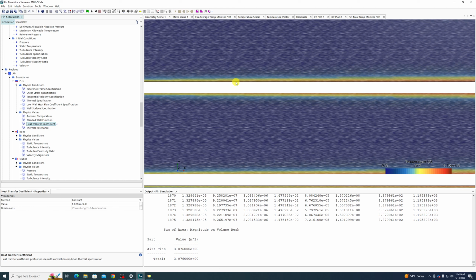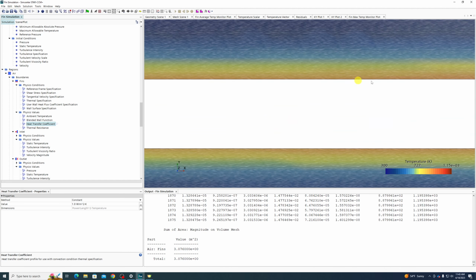What the convection thermal boundary condition assumes is that you have a wall. So this black line, you have a wall. It's figuring out what's happening on this side of the wall. You're telling it that on the other side of this wall, somewhere in this white space, there's another fluid at some temperature interacting with some heat transfer coefficient through a wall with some thermal resistance. So if you have an insulated wall on, I don't know, a house, you know the air temperature outside is blisteringly hot, 120 degrees Fahrenheit.